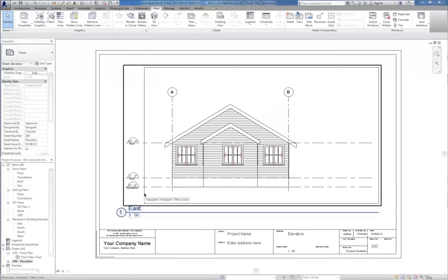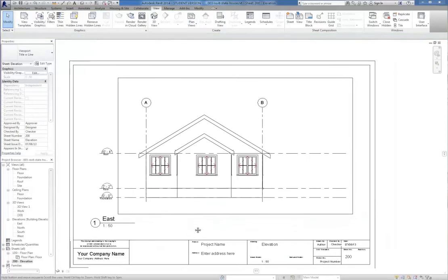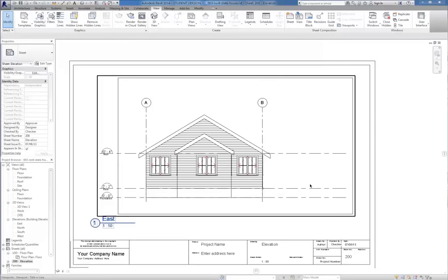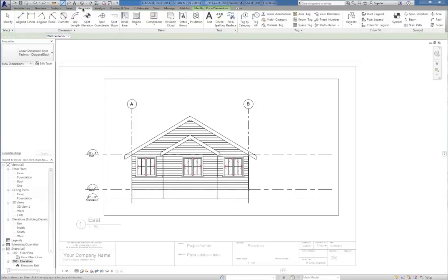That's looking alright. And then what if I want some dimensions to show the height between here and here? So what you can do is double click on here and put it in here. And I think all the dimension lines and things like that are under annotate. So if you click on annotate, we'll try aligned. You can hover over stuff and it'll measure it.